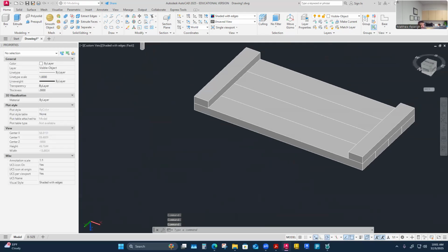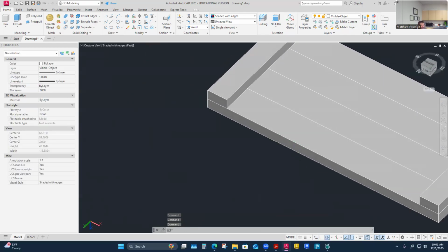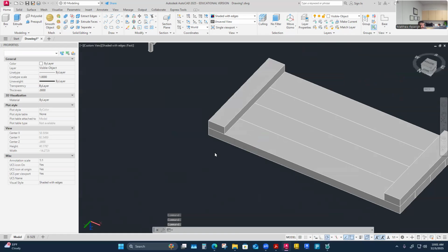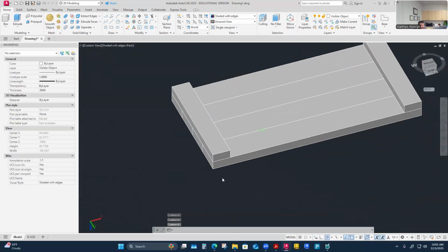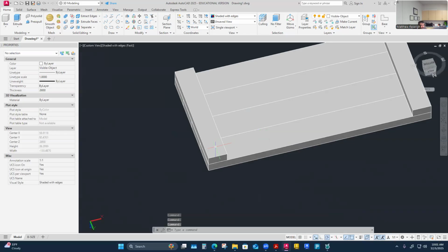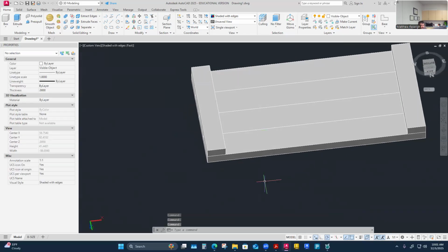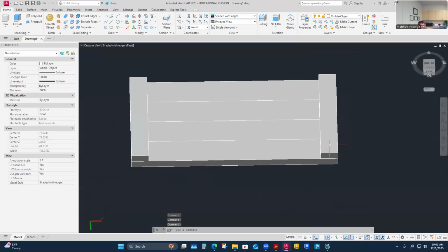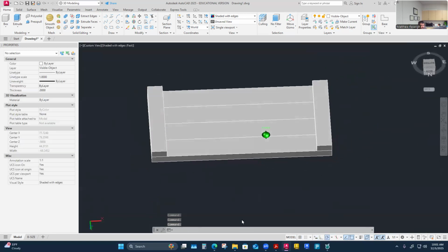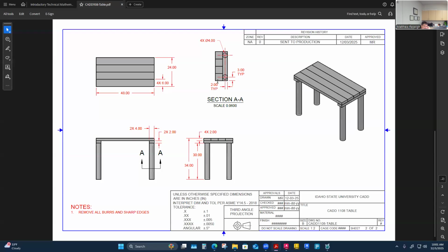And now we just need some legs. And I think I ended up using just my array command for legs. So I think I drew one leg here where it goes, and then I just arrayed it. And so I just need to find out where that would go. And I could put the first leg on any corner here, but I think, or you could copy and paste them over too. But the way there, I don't have the exact grips on any outside edge where the center of that would be.